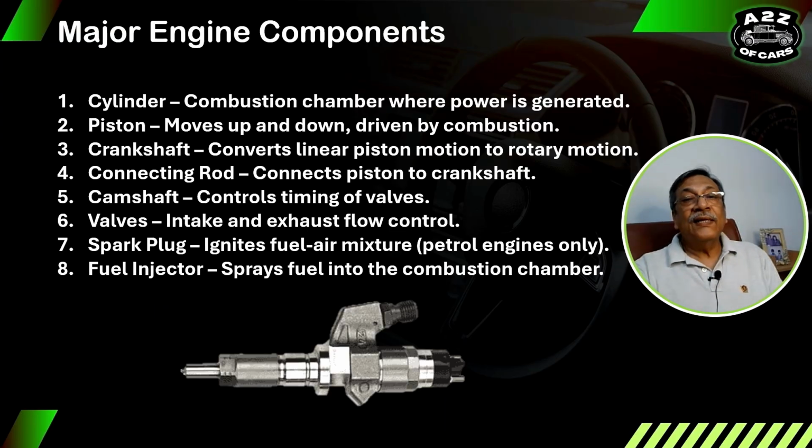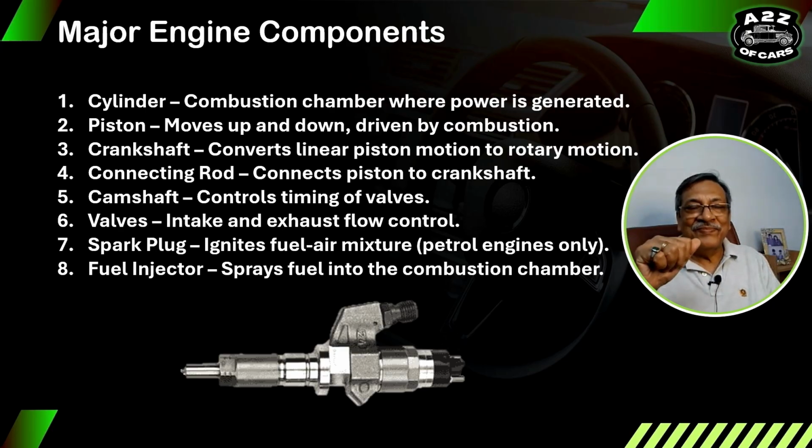Fuel injectors. Now don't confuse. There are fuel injectors in petrol also, and there are fuel injectors in diesel also. In diesel, the fuel injectors are directly fitted onto the head. They inject the fuel directly into the cylinder.